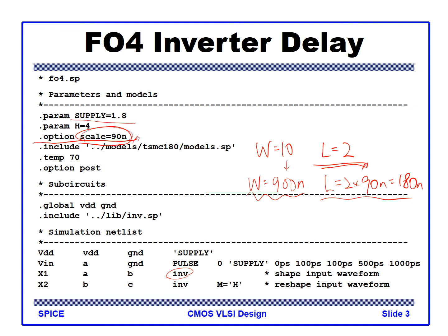And also the supply parameter is defined like 1.8 volt, so this parameter is called here. Using a parameter is like using the quote notation, as shown in here, right? So the sub-circuit definition is called by the inverter like this. The inverter SPICE tag is included, right? Okay.